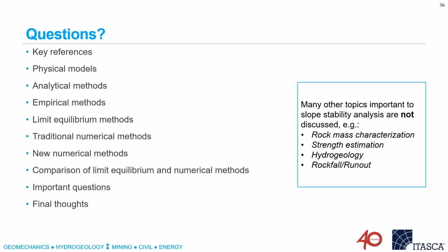The first point is, let's talk about what it does. What the D factor does is it reduces the friction and the cohesion of the rock mass. Now, people have looked at this and most people have concluded that, yeah, the cohesion certainly drops, but the friction angle really doesn't. In fact, the friction angle at low confinement, which is what we're most concerned about in slopes, can actually increase. And there are papers that demonstrate that. So first of all, what the D factor does doesn't agree